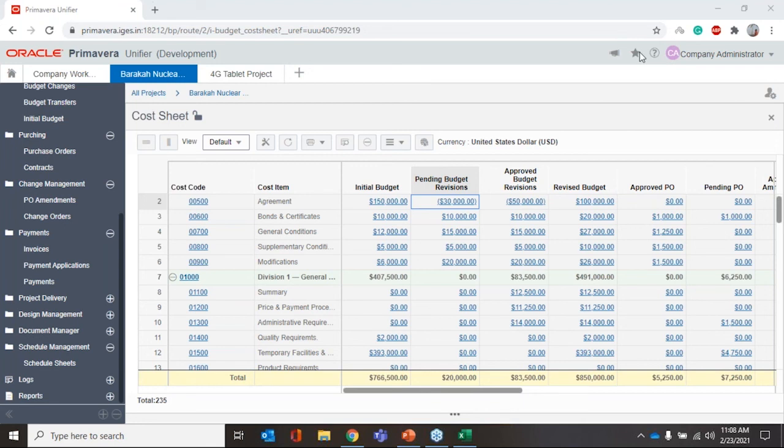However, Unifier also has a scheduling area, so sometimes if you would like to update here itself, you can do it. But the typical workflow is that planners traditionally use Primavera, so we don't touch upon it. We normally integrate P6 with Unifier, so the planners continue to work on P6 with their scheduling, and it can push the relevant required data into Unifier.